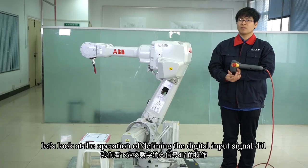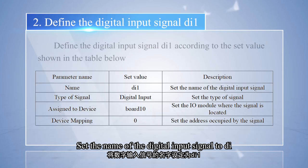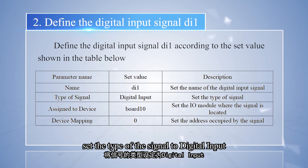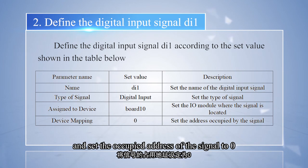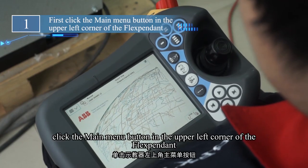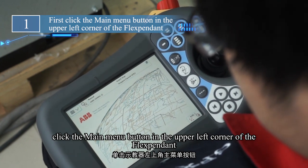Next, let's look at the operation of defining the digital input signal DI1. Set the name of the digital input signal to DI1. Set the type of signal to digital input. Set the I/O module where the signal is located to board 10, and set the occupied address of the signal to 0.